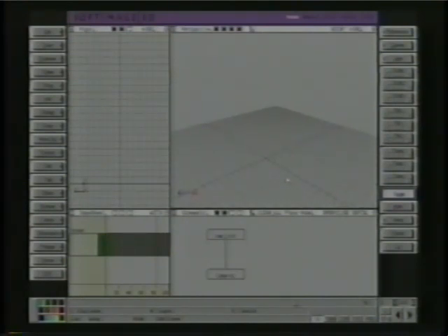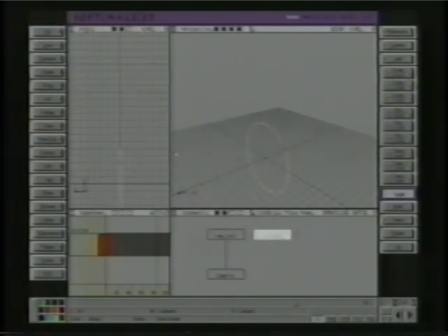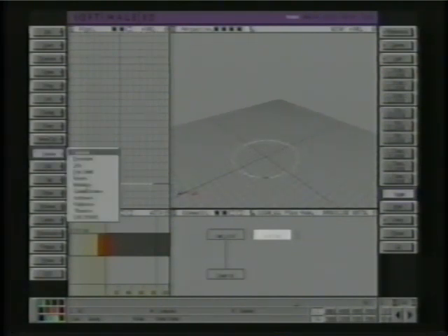Now I'll talk about just a couple of alternatives to skinning. There are lots of other things you can do. First of all, let's get a circle. I'm going to extrude this rather than skin it. It's very simple. Rotate that 90 degrees. Surface,